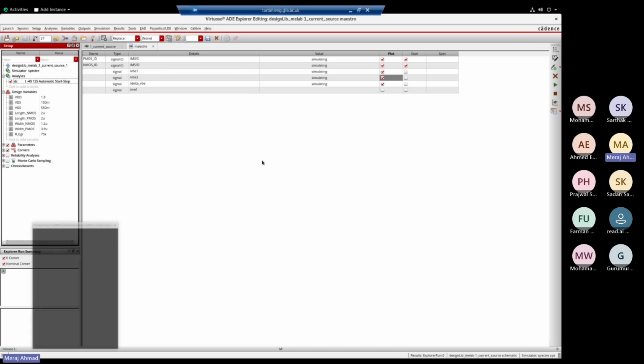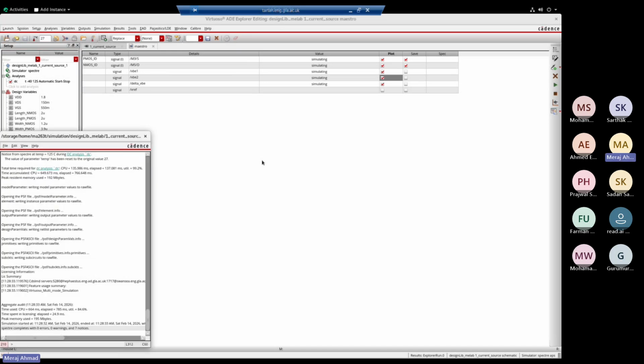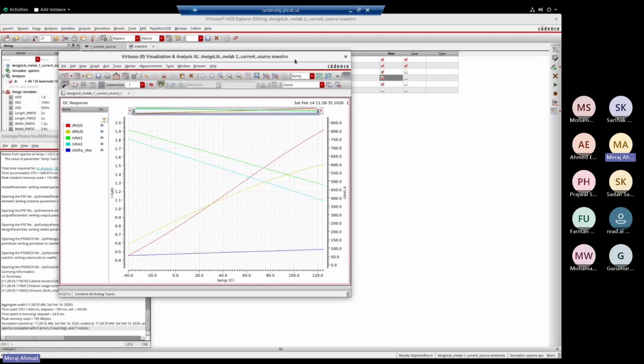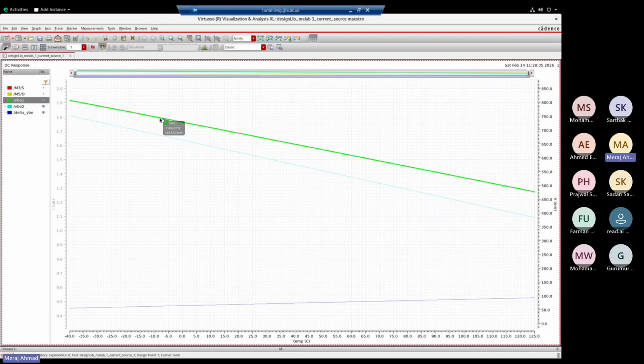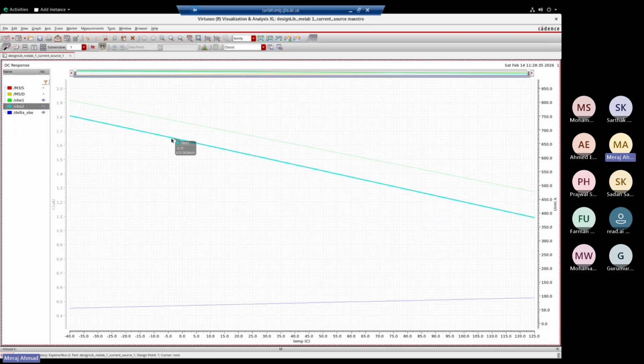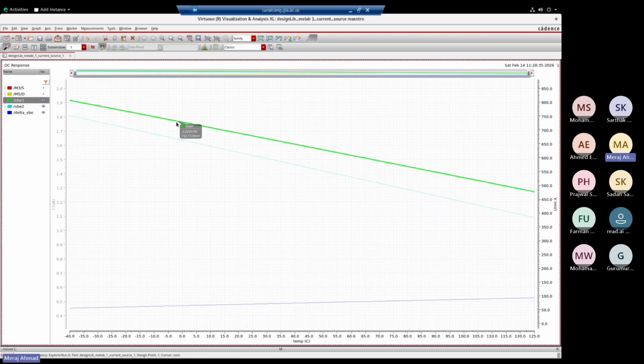For more details, you can refer to any analog IC design book or any video lecture. The main thing is how we are extracting some of the current. VB1 is where you inject a current but your area is minimum; here you have increased your area. This is how your VB is changing with temperature. In bandgap, this is called CTAT, complementary to temperature.